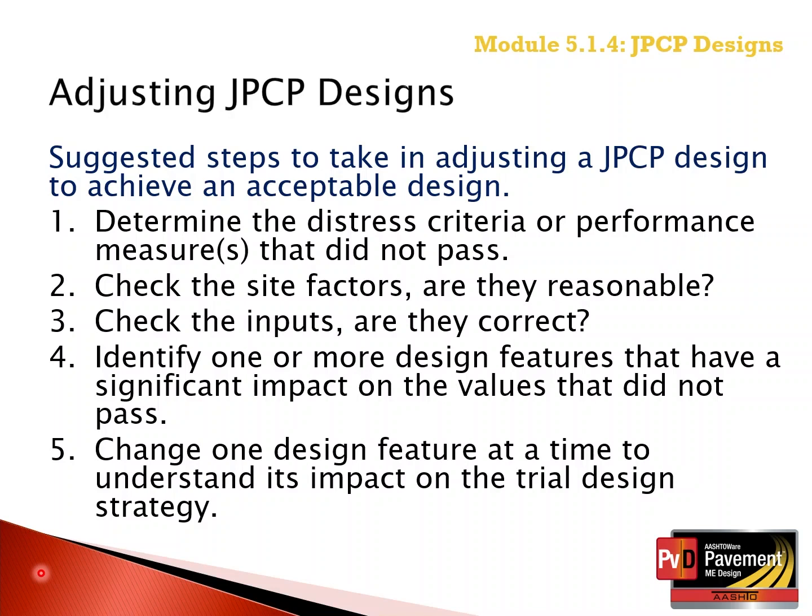It's generally not suggested to change two or more design features at the same time to achieve an acceptable design unless you're using the optimization feature of the Pavement ME software. So it's generally suggested to change one feature at a time so that you know its impact on the distress criterion or performance measure that did not pass.